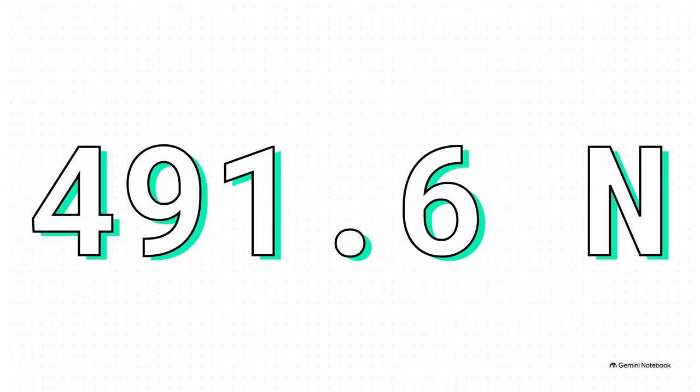But is that 172.6 newtons actually available to us? Let's check the maximum capacity. We multiply our normal force of 1404.5 by our static coefficient of 0.35. That yields an absolute maximum available friction, our Fm, of 491.6 newtons. Because our required friction is only about 173 newtons, it is well below that 491 newton breaking point. We are solidly in the safe zone, proving conclusively that the block is in stable equilibrium and will not slide.